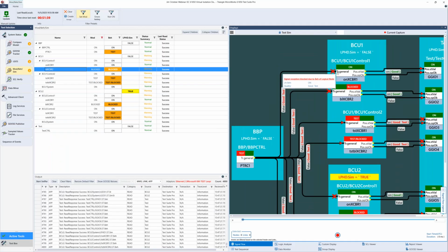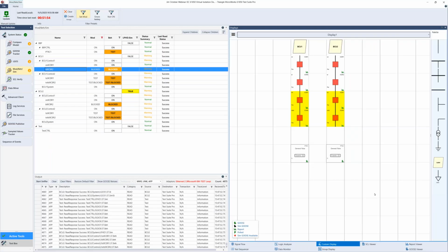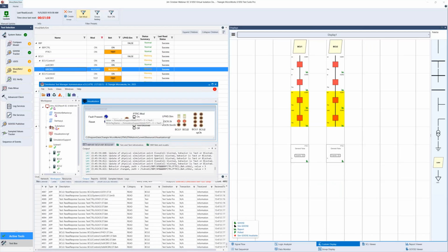So, okay, that means now if I operate here, we will only see the third breaker open in both cases. The other ones should stay closed. So let's do that. Let's again create the trip. And we see this one has op OK, those ones don't have op OK, this one has op OK, but they don't operate because it's blocked. These ones have operated. We see here those two switches have operated. So everything so far worked as expected.